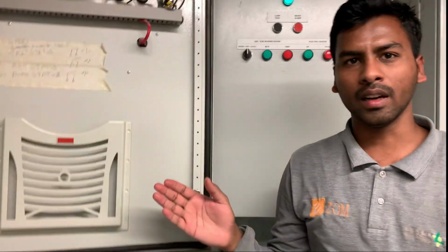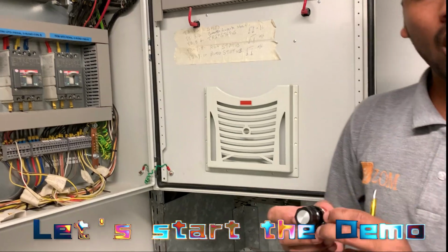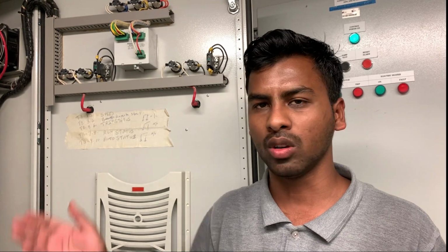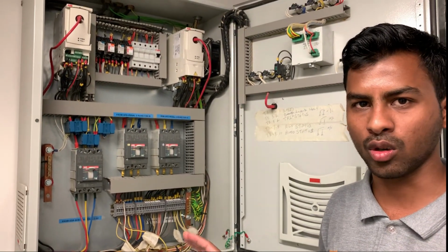So I have explained the physical terminals of the VFD, and also the parameters. Now I will make a demo. I will run this VFD through a potentiometer, because this fan will run when there is a fire in the building. But for now, we don't have any fire alarm, and there is no actual fire in the building, so this motor will not run. So what I will do is supply 24 volts to terminal 4, because I already explained that when there is 24 volts on terminal 4, it will run. The motor will run, but now there is no 24 volts.